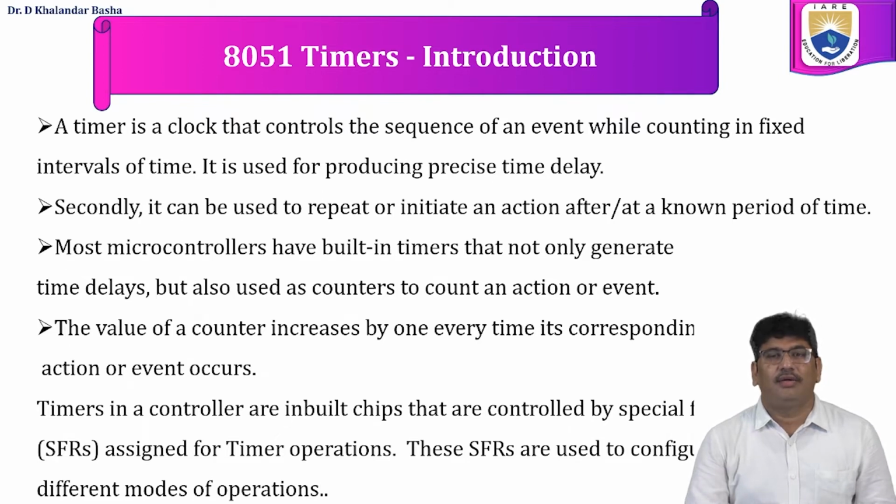Timers in a microcontroller are inbuilt chips that are controlled by specific registers, that is SFRs, special function registers assigned for timer operation. These SFRs are used to configure the timers or counters in different modes of operation.